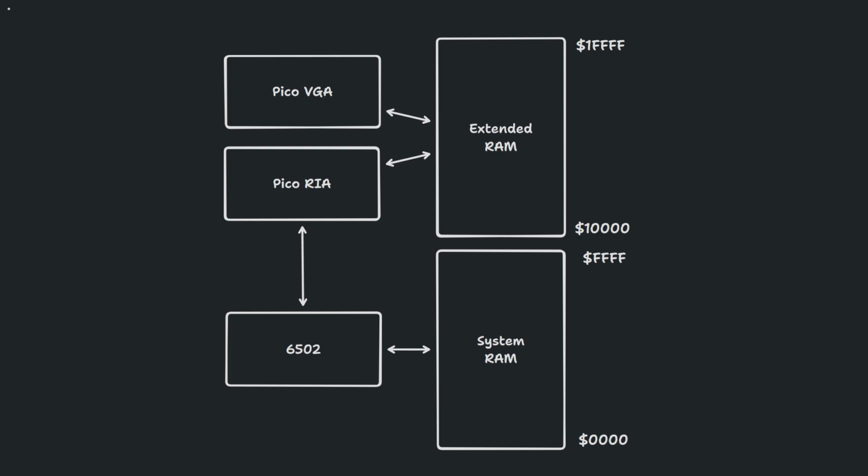There's no ROM in the traditional sense. This is all RAM. To run a 6502 program, it has to be in system RAM because there's no ROM attached to the 6502. Well, there's no ROM hardware, but there are virtual ROMs which we can load and run. These virtual ROMs are files that need to be created. That's what we're going to explore.